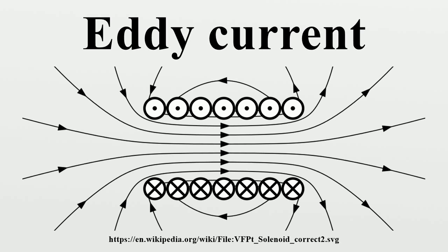Skin effect. In very fast-changing fields, the magnetic field does not penetrate completely into the interior of the material. This skin effect renders the above equation invalid. However, in any case, increased frequency of the same value of field will always increase eddy currents, even with non-uniform field penetration. The penetration depth for a good conductor can be calculated from the following equation, where δ is the penetration depth, f is the frequency, μ is the magnetic permeability of the material, and σ is the electrical conductivity of the material. Diffusion equation.